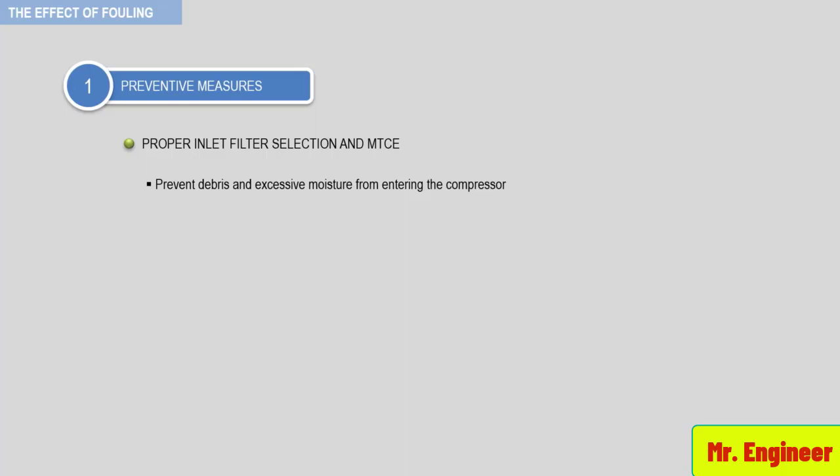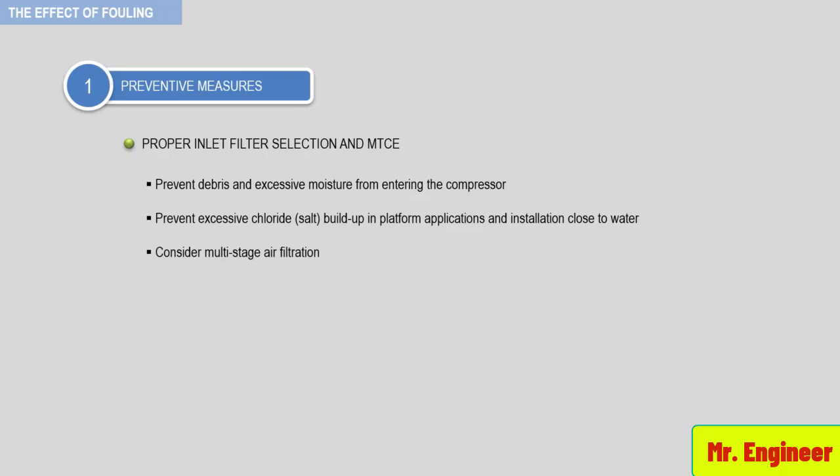In platform applications and installation close to water, special designs must be used to prevent excessive chloride buildup. For this, my advice to you is to consider multi-stage air filtration.